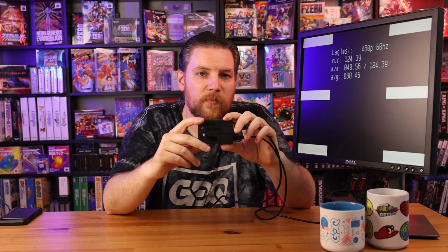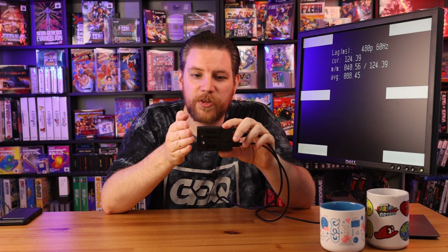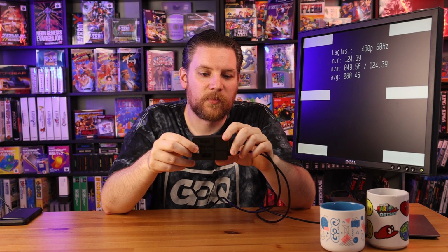One note about the Time Sleuth only having 60 Hertz signaling, I wish there was a secondary dial to adjust the frequency separate from the resolution. Right now this only does 60 Hertz, no other refresh rates. I wish this had settings for 50 Hertz for PAL testing, or 120 Hertz or higher for high refresh rate monitor testing. So this device is not perfect, but this gives a good example of how different equipment adds different types of latency to the signaling. Now let's go check the complex video chain that I've built on my entertainment center.